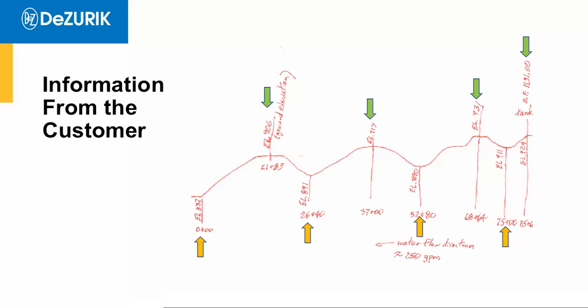And I was really happy about getting this until I realized I have to rethink something or else I'm going to have a mistake. And the clue is on the paper here, on the screen. And it's about water flow direction. Normally we think, and the program thinks, that flow goes from 0, or the lowest number, to the highest number. Well, in this case, they show the flow starting at 8560 and ending up at 0, so it went backwards.